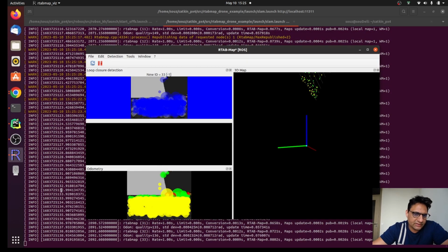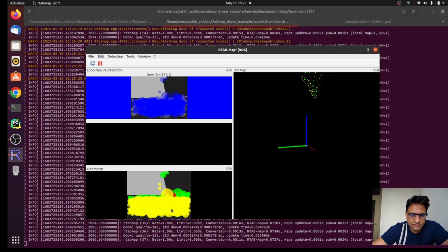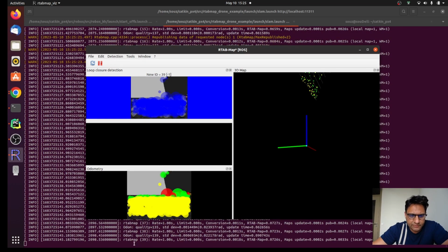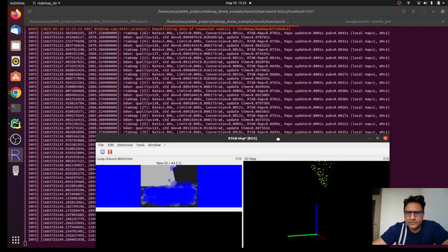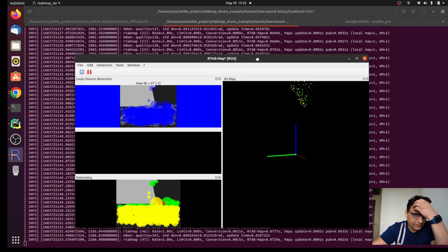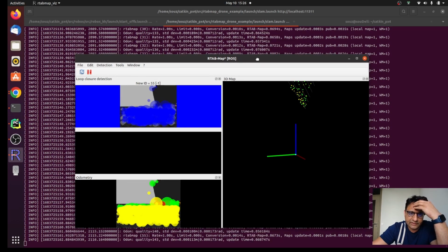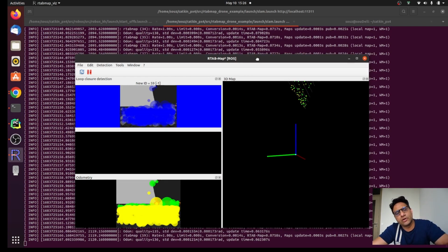Other than that, it's now completely integrated with move base locally. You can see your odom topic, you can see the RTAB-Map topic, and you can see all the other relevant costmap and conversion. The next thing would be to figure out the camera, and then figure out the teleop or QGroundControl to move the drone and get this map done. And we'll see how we can save this information, and then we can run locally to avoid obstacles.